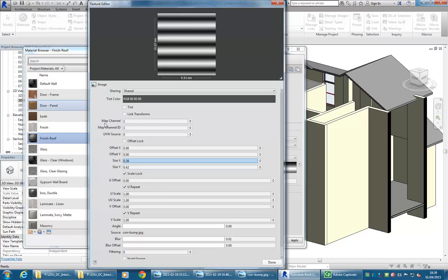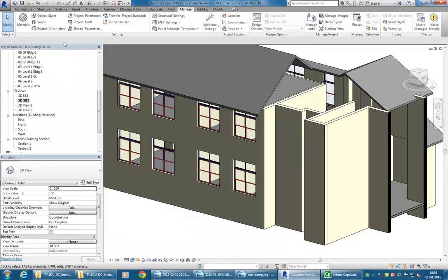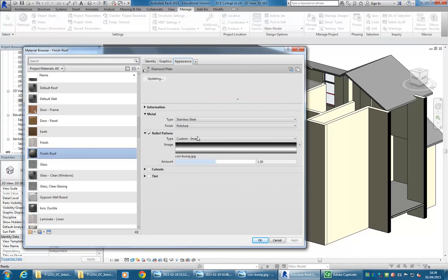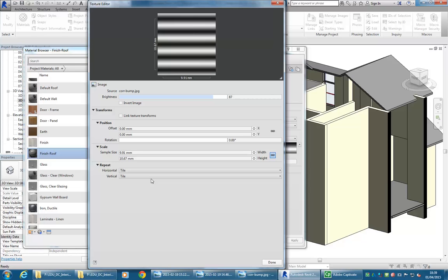It's giving us the wrong properties. So if you don't see the size in millimetres, and that's what you're looking to change, the trick there is just click Done, click OK, get out of it, come back in, and go back to where you were. Here we are, click on the swatch again, and now notice how it's completely different. It's just a bug that they haven't fixed for a few releases. So easy to fix though. Once you go out and then go back in once, it should be right from then on.